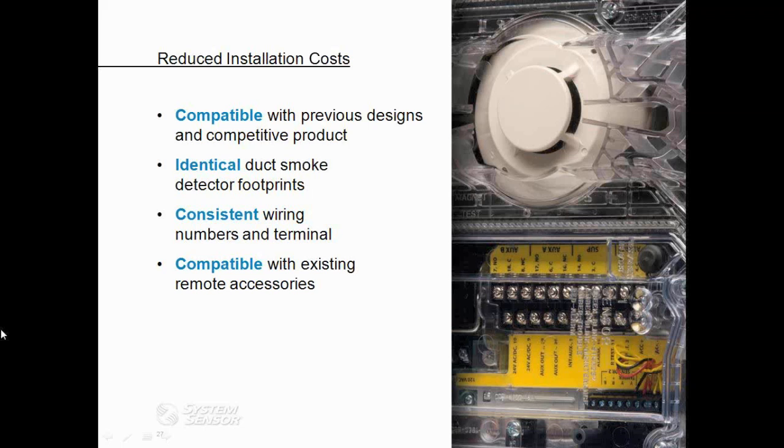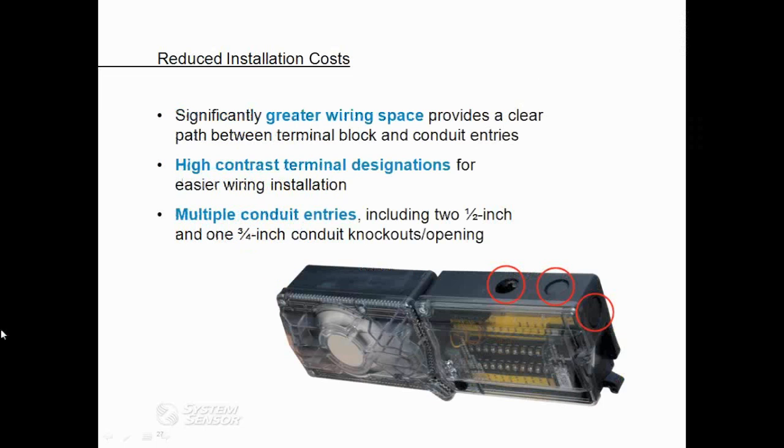And the InnoVair Flex duct smoke detector can be tested with our new line of remote test accessories, but can also continue to be used with our old style remote test accessories. So that's helpful where if your duct smoke detector needs to be replaced, you don't have to replace all the other peripheral devices that are wired into it.